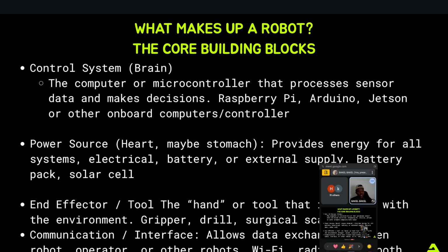But for the drones, we mostly have 2 computers. One that is going to handle high-level tasks, autonomy, as we say, and one that handles lower-level tasks like sending motor commands. Say, for example, you want the drone to go forward. For a drone to go forward, the revolution of the first two will drop a bit. The revolution of the last two will increase a bit, and then the drone tilts forward and moves